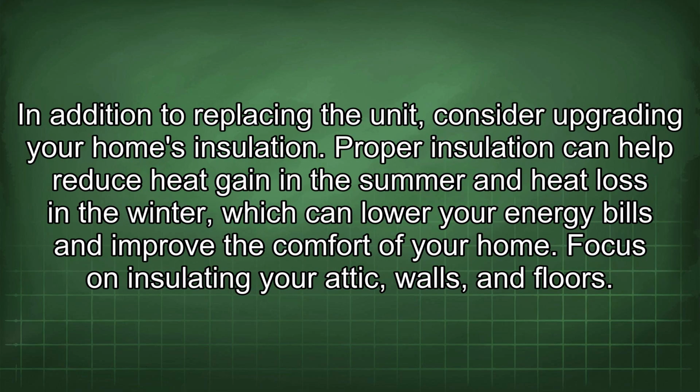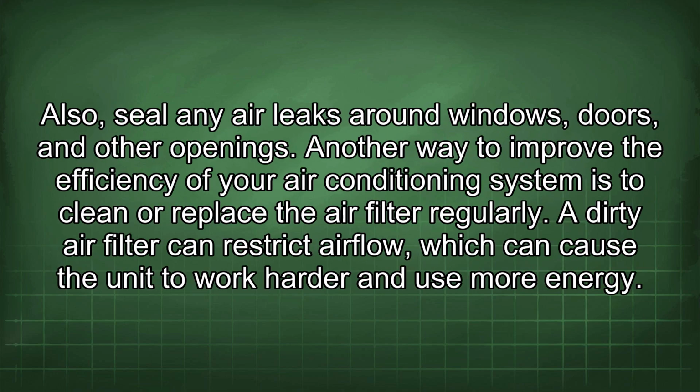In addition to replacing the unit, consider upgrading your home's insulation. Proper insulation can help reduce heat gain in the summer and heat loss in the winter, which can lower your energy bills and improve the comfort of your home. Focus on insulating your attic, walls, and floors. Also, seal any air leaks around windows, doors, and other openings.